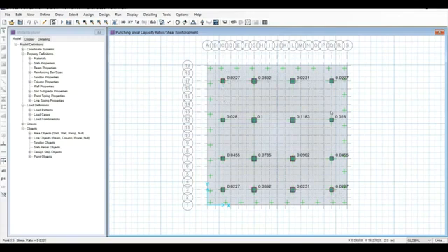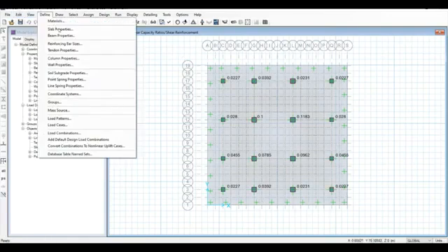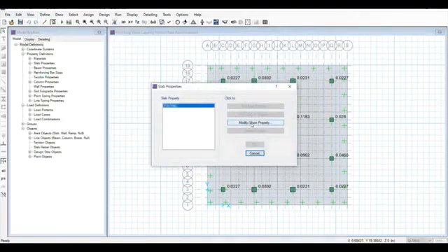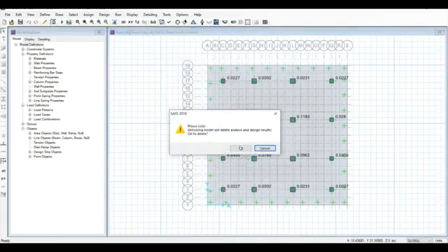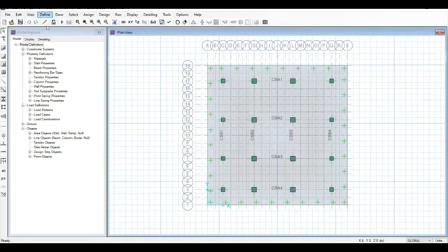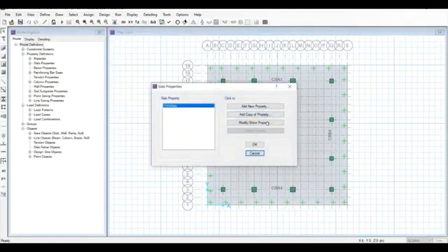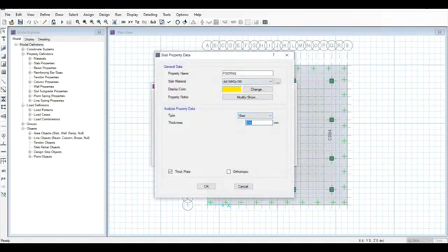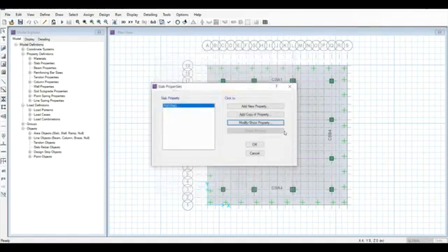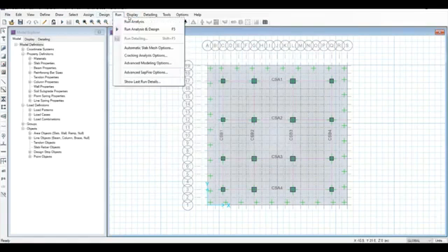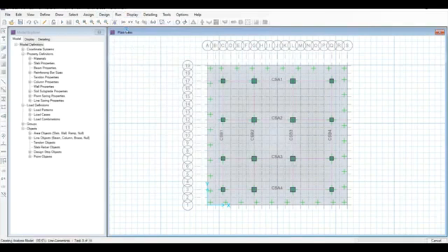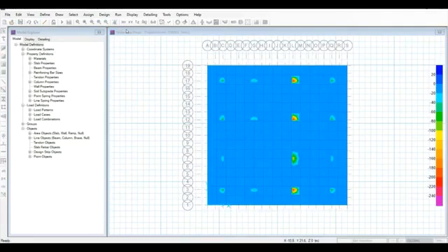If we have any different values here, then we need to go for define and change the slab properties of footing. Modify. As we are in unlock position, we need to unlock it first. Define slab properties, footing, modify our slab footing, and change here the values from 200 to 500, and then click OK. Click OK, and then you can go for analysis again. As we have already got these values as safe values, there is no need to do this. As all our values are the same.